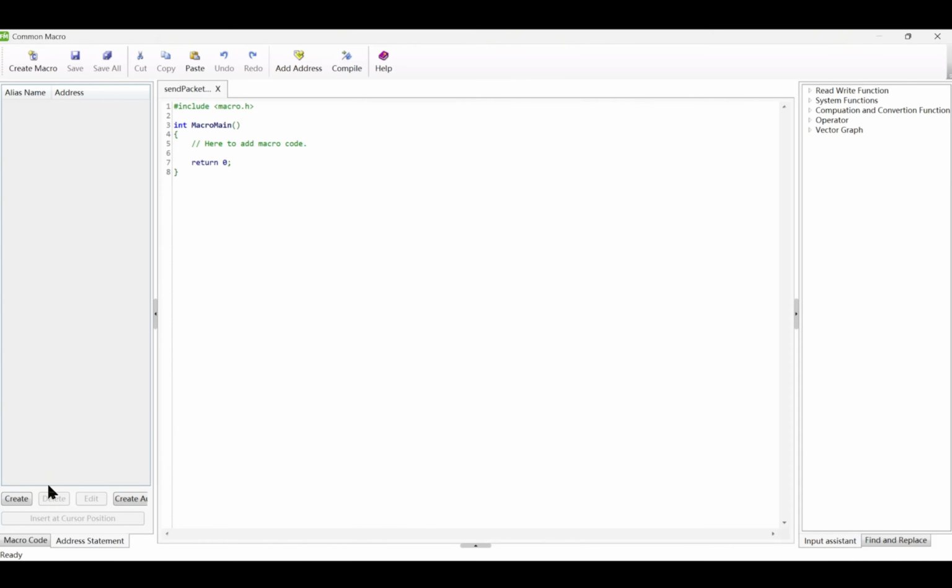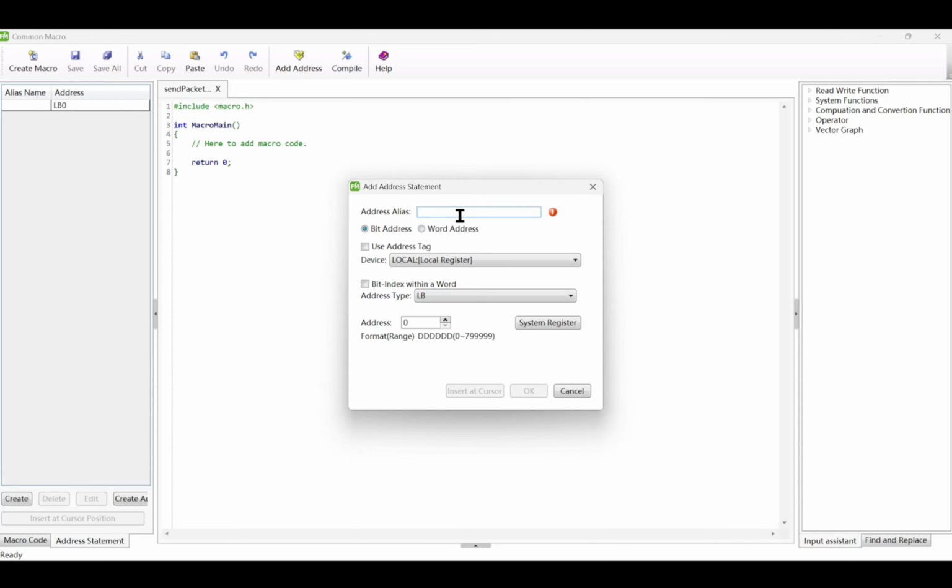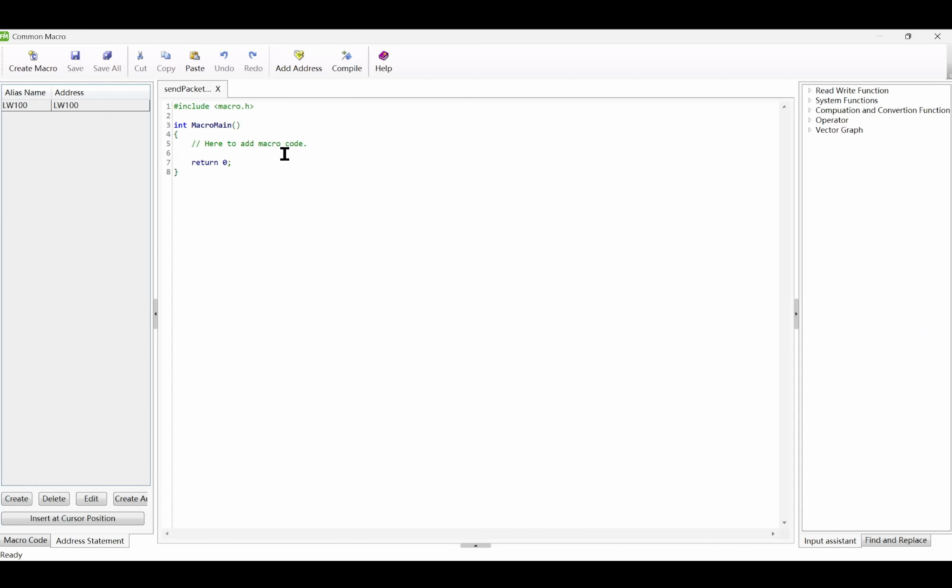To create the ASCII macro, which is to send a human-readable string, we start by defining an array of 100 characters, sendBuf, initialized to 0. We then use the sprintf function to copy the string into this array. Next, we send the contents of sendBuf using the outport function, specifying the port number as 0, the data to send as sendBuf, and the length of the data as strlen(sendBuf).